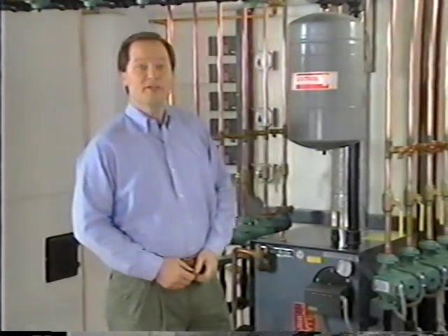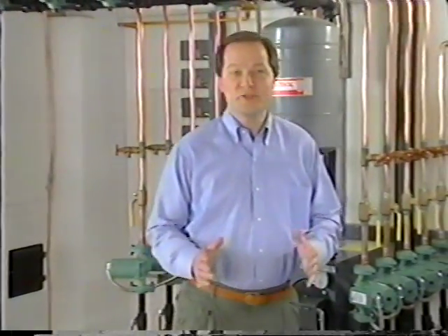You should now have a basic understanding of hydronic heating systems, how they operate, and how they're piped. Next, let's discuss the zoning of hydronic systems, why we would want a zone, and some basics behind zoning. You might wonder, what is zoning? What does zoning mean? A zone system is nothing more than a room or group of rooms in a residence or commercial building which are served by separate piping circuits and a control devised to maintain temperature.